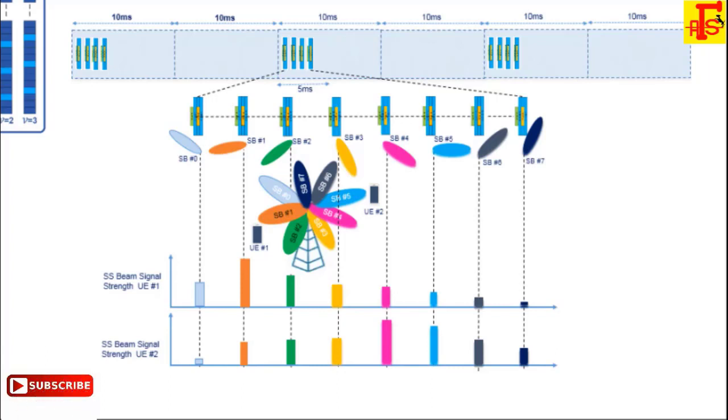So after reading, by using the DMRS reference signal, you decode the PBCH information where the MIB and SIB are located. Now the MIB and these are the configuration, these are the parameters related to the cell. Now the MIB is decoded. So the remaining part I will discuss in the next video.